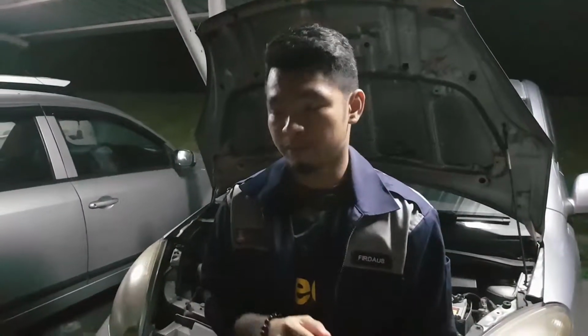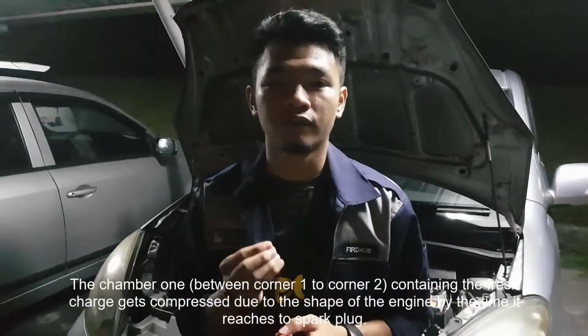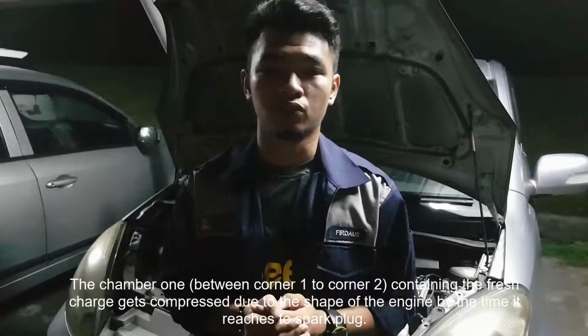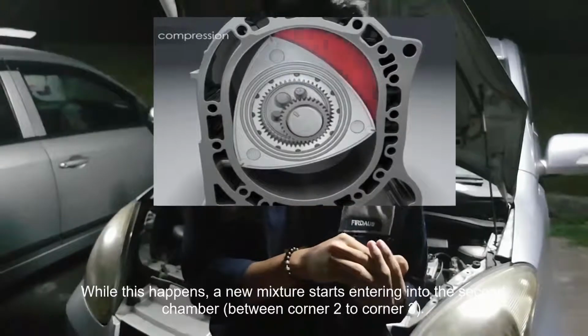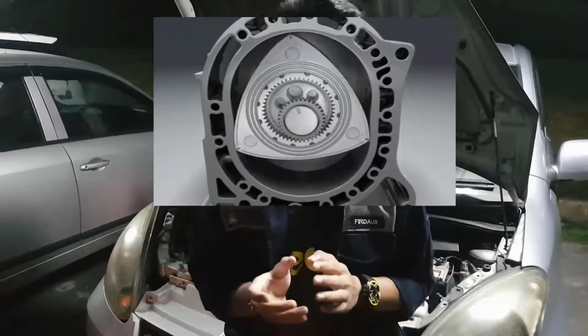Besides that, part 2 is compression. The chamber 1 between corner 1 to corner 2, containing the mixture, gets compressed due to the shape of the engine by the time it reaches the spark plug. While this happens, a new mixture starts to enter the second chamber, which is between corner 2 to corner 3.